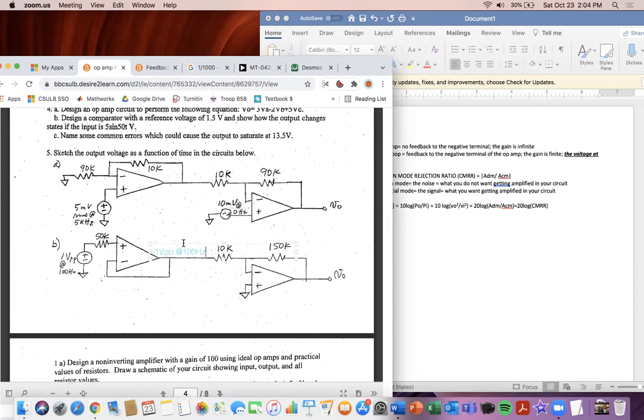And then if I know that's going to be my voltage on this negative terminal here, I can redraw this so it makes more sense to you guys. So just ignore everything over here now, since we know what the output voltage was. And it's going to look like this, our 1 volt peak to peak at 100 hertz. And so now I have this configuration, and this reminds me of an inverting amp configuration. And if we know inverting amp, it's V out equals Vi times negative RF over RS.